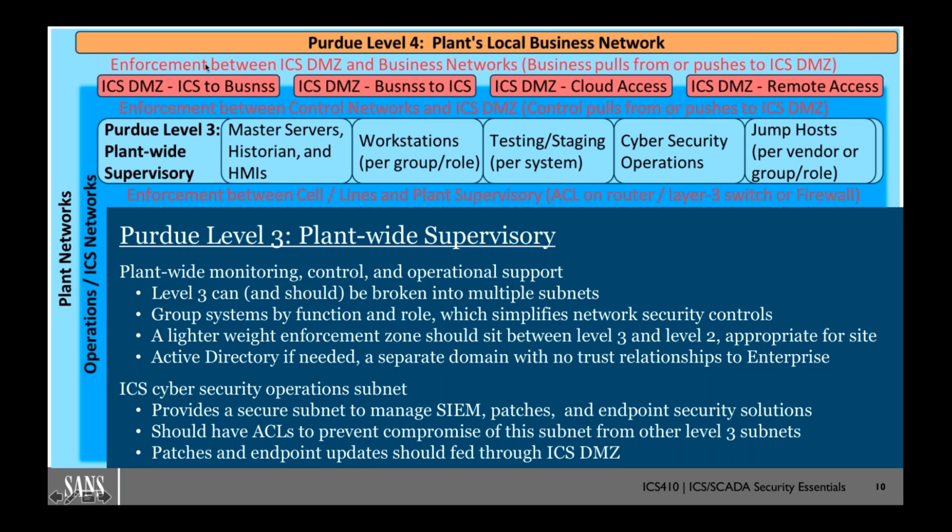So your question stems from the fact that I mentioned that often we have 2 firewalls for political reasons, because we have an enterprise team managing one side, and then we have an ICS cybersecurity team managing the other side. As of right now, I would say most of the companies out there have tried to unify all IT and cybersecurity efforts into a single team. The problem with that is those team members generally do not understand the specific needs of the ICS zones or the delicate nature of the ICS areas, and so it actually leads to a lot of problems.